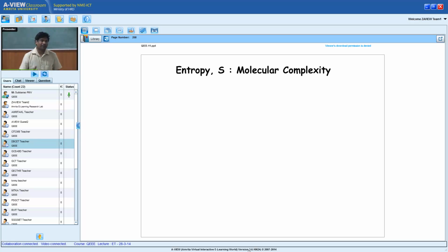When will that happen? If you can do the entire heat transfer at the highest temperature, because everybody demands some heat transfer, isn't it? So I'm demanding some heat transfer. If that heat addition occurs at the highest temperature, see del Q by T, minimum randomness creation. In the same way, whenever I'm rejecting heat, you need the lowest entropy creation appropriately. This is the greatness of the entire thing.